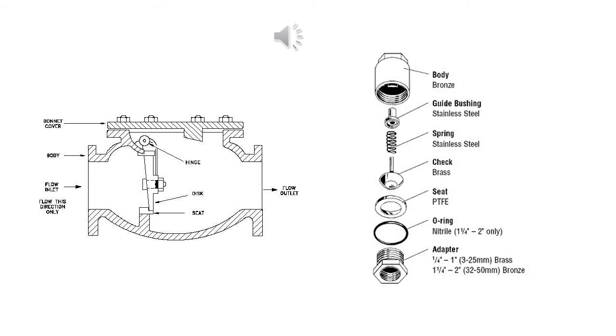The picture on the left is of a swing valve. Care must be taken that it is positioned so the disc will operate properly. Swing check valves should be mounted in the horizontal position, but may also be mounted in the vertical position provided the disc is opened by the flow and not by gravity. If positioned wrong, you risk the disc being always open because it is controlled not only by flow but also gravity. The picture on the right is a blow-up of a spring check valve. Its positioning is dependent upon the direction of flow arrow imprinted on it.